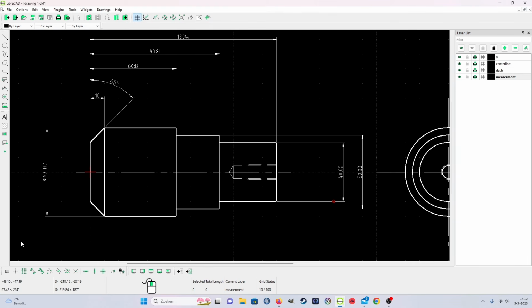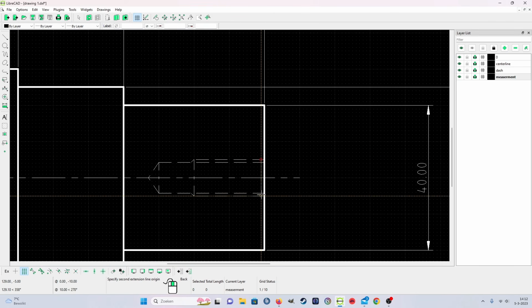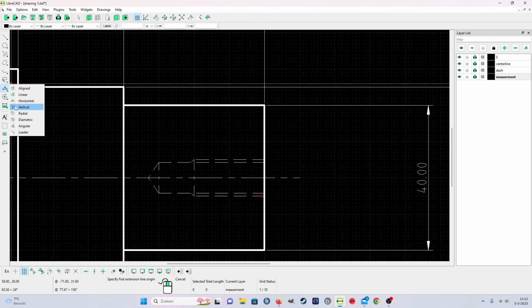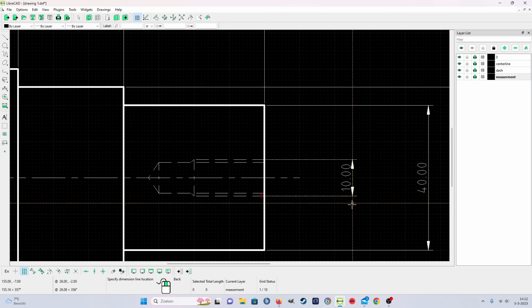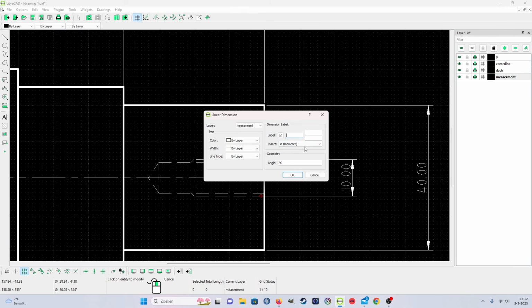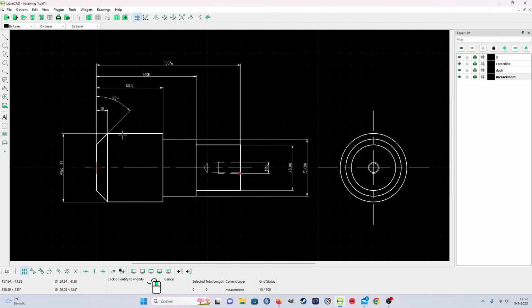Okay, now with the thread hole, vertical. Let's put the grid on and let's make it a little bit easier for me. From here, I know that's 10 mil. Oh, I put the wrong one. If it's wrong, just press your right mouse button and you can start over. Yeah. From here to here. Also properties, and that's of course M10. Like that. We got nearly everything.